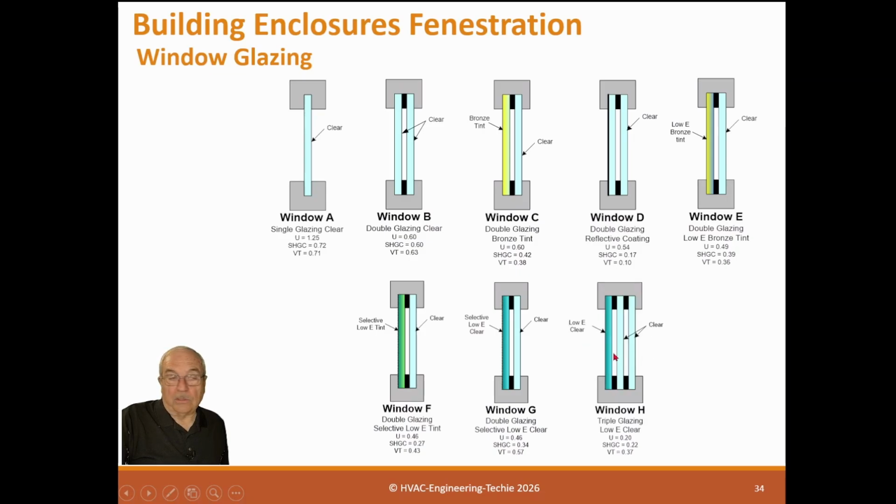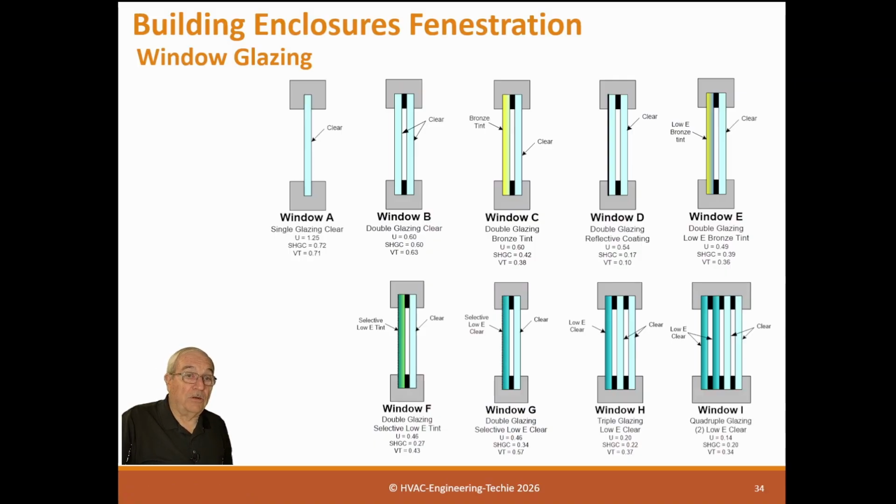Now this is a triple glazing, and you can see that the triple glazing low E is down to 0.20, and its visible transmission now is down to 0.37. So triple, we don't see many triple pane because they're very expensive, but they do help. So triple pane. You also make a gain. I've never seen one of these, but I guess you could do that.